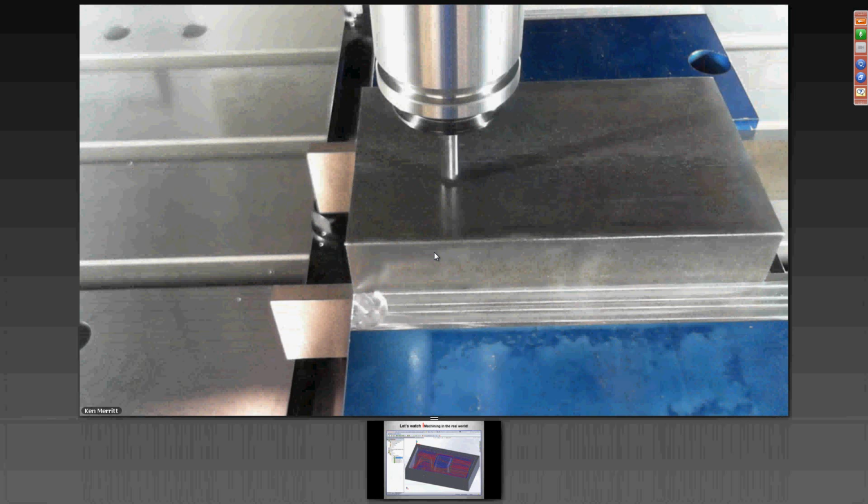Yeah, absolutely. Let me fill you in on what's going on here. This is a 1/4-inch diameter tool. This is a 3-fluter. We're working with a 3x5 block of steel, 1 inch deep, and we're going to be cutting at 625 thousandths depth of cut. The steel grade is 1018 cold roll. And I think you're going to be fairly well impressed with what we're about to do here. So let's go ahead and get it started, and then I'll tell you what's going on.